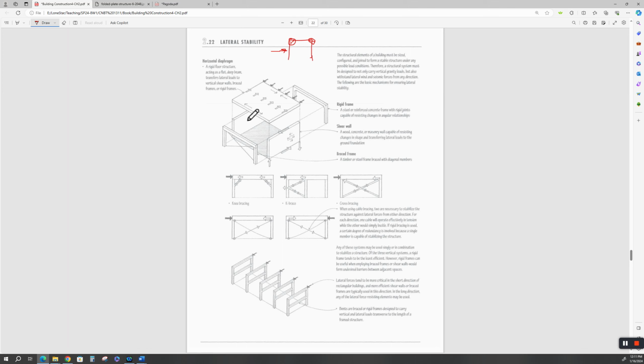Now, you can use your floor systems. We call these a diaphragm system. They can be cast-in-place concrete. They can be precast panels that are welded to the beams and columns. There'll be weld plates up in here to make it a rigid structure. It's a horizontal diaphragm. Your load-bearing walls, they carry load.